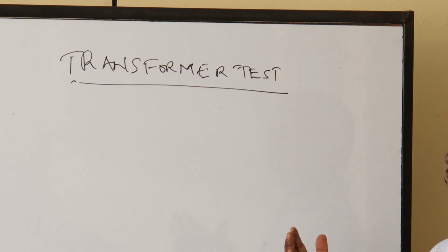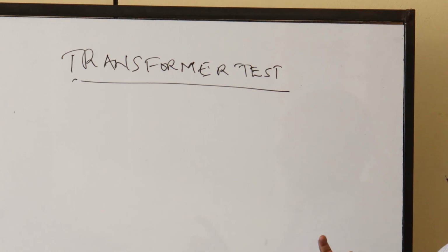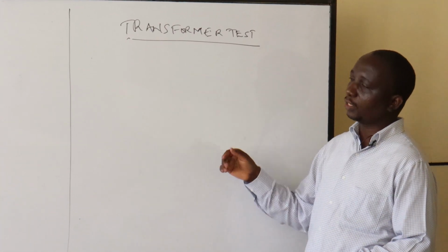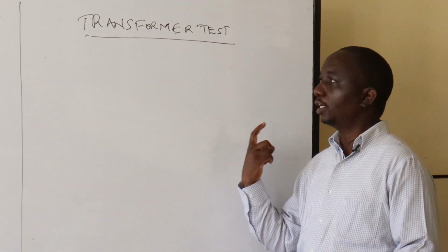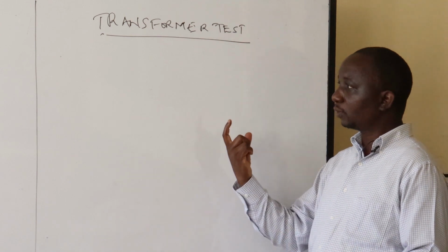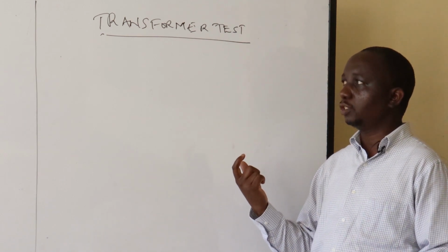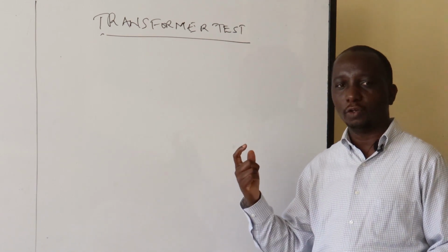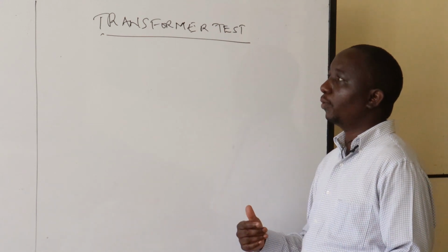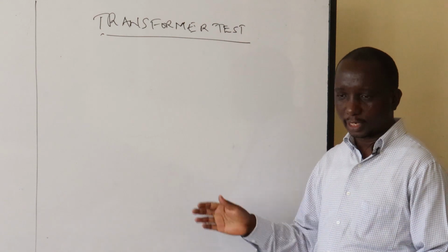The reason it's a no-load test is because you want just to determine the heating that's developed across the core of the transformer due to the movement of the flux. As a result of that, we shall be eliminating the secondary winding out of the circuit. That one will not give us the load test. When the secondary winding is included in the circuit in the test, then we talk of the load test. So basically, these are the things we need to be aware of.